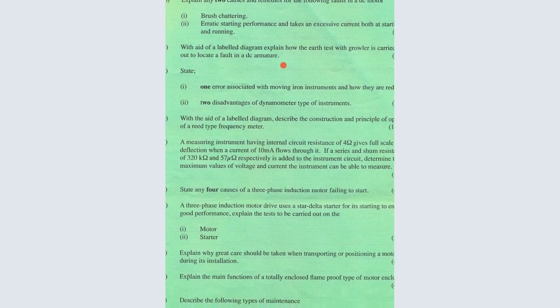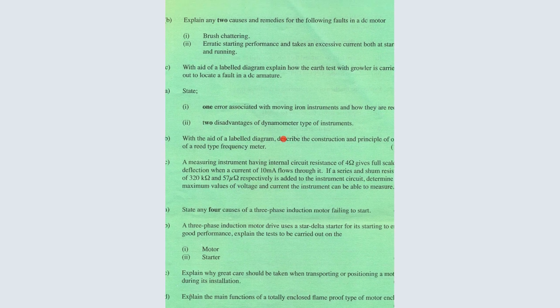Maybe the current is exceeding the rating. Maybe the motor is overloading. When the motor is overloaded, it draws more current, which means it will use more current when starting and also when running. Another problem that will cause that is when you don't supply it with enough voltage according to the specifications, enough for it to pick up and get enough torque. So that can also be another problem.